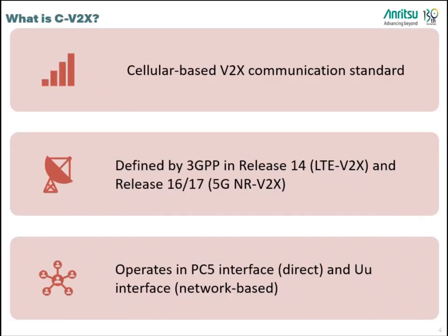So what is this V2X? It comprises two technologies: the PC5 communication and the cellular technology. When we come to cellular, first it is the LTE V2X, which is defined by 3GPP release 14. And moving on, as new technology evolved, like 5G, the NR-V2X is defined in release 16 and release 17. So both these technologies, PC5 and the Uu communication, or the network-based communication, comprise the overall CV2X.